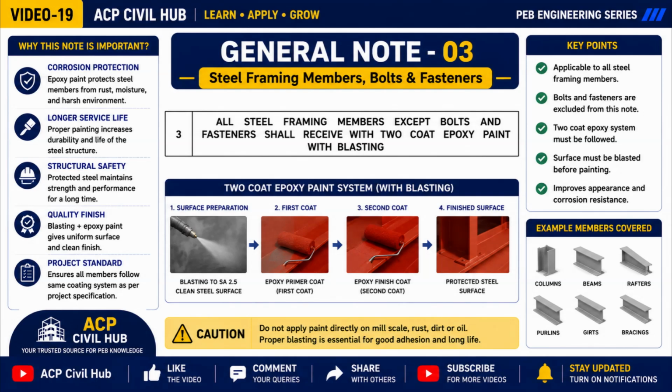Now let's understand the third general note, which specifies the surface protection requirements for the steel structure. This note states that all steel framing members, except bolts and fasteners, must receive a two-coat epoxy paint system after proper blasting. Before painting begins, the steel surface must first be cleaned by blasting to remove rust, mill scale, dust, oil, and other contaminants.